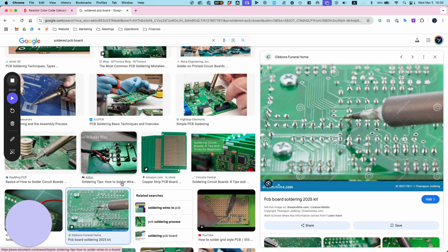Now, because we're soldered, there's no way for me to easily break another connection. But if I was to break another component and measure the current, it should be 0.003, 0.004, right? Because current is the same throughout. But these are all soldered on, so it's hard for me to do that. If I had the breadboard, I could do that easily, take out things and then measure anywhere along the circuit, and it'll all be the same current. All right, so there's that.